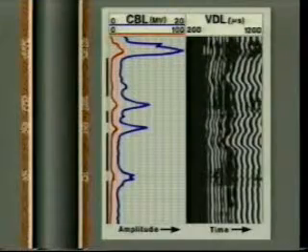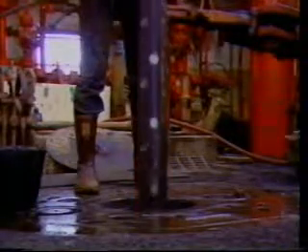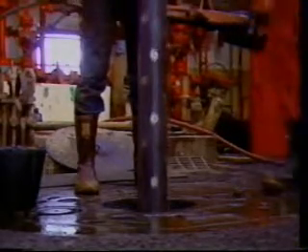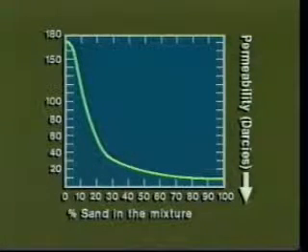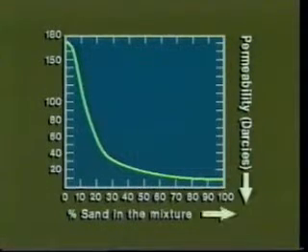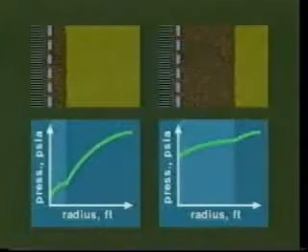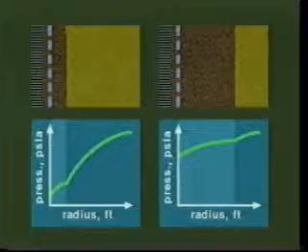Many engineers believe that, provided the casing is securely cemented and the pressure differential between the casing OD and ID is not great, such high-density perforating should not cause casing failure. It should be noted that permeability will be reduced and a greater pressure drop will occur where formation sand mixes with the gravel pack. Thus, the gravel-formation sand interface should be placed as far from the perforation tunnel as possible.